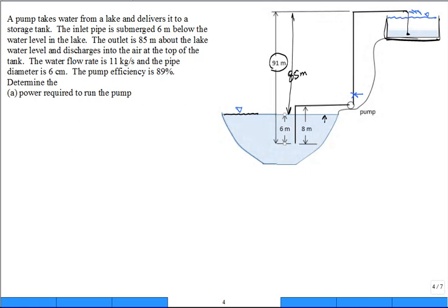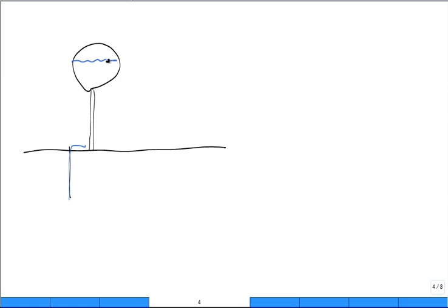And this is a classic thing too. As you'll see, I'll have a water system. Here's my surface. Here's my well. I pump the water out of the well. It goes up into a good water tank, a water tower, right? And so the water tower is sitting up here full of water. And the well is going to splash it out at the top of the pipe, and then it'll fill up the tank. Because if anything ever goes wrong when you shut this pump off, you don't want it to suck it back out, the siphoning, and push it back into the ground. True? Does that make sense?